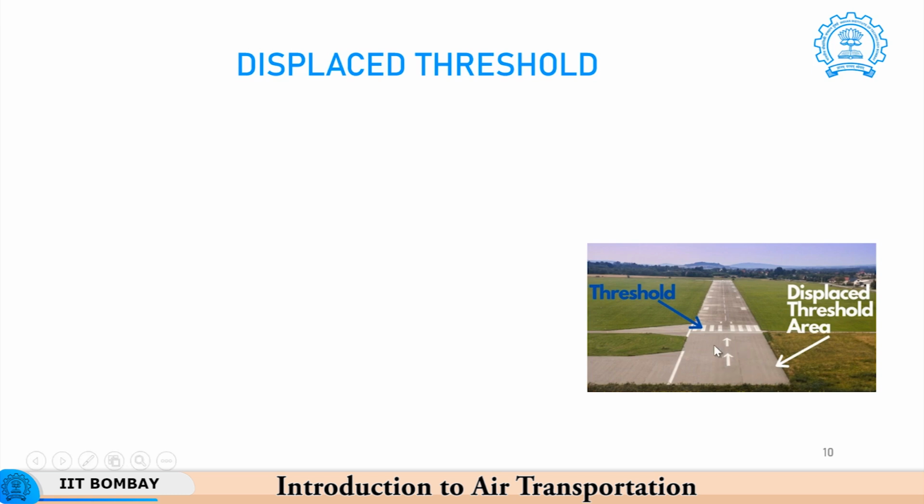you can also see these two white arrows on the airport. In all airports, wherever you have a displaced threshold, if it is substantial in length, then we normally put white arrows indicating the direction at which you are supposed to land, and also it is important to note that the threshold here is displaced. So, this much runway length. So, although the runway is there, it can take all the loads, it can also allow you to do a takeoff, but because you are forced to displace the threshold, therefore, you will be asking the aircraft to be aligned here and then go for takeoff,